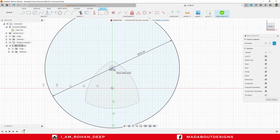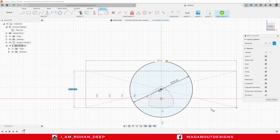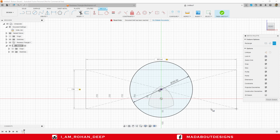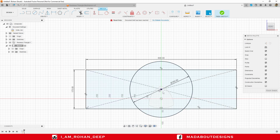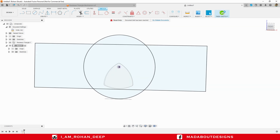Select this center as the center of the rectangle and give it a dimension of 600 by 175 mm. Press Enter. Let's hide the constraints and the construction lines so we can have a clear view of the current sketch. Finish sketch.